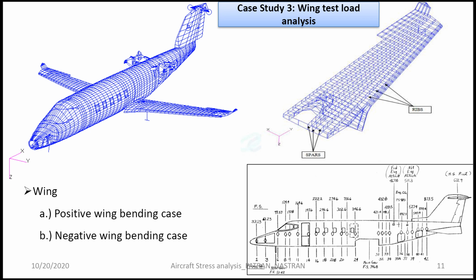So moving to another case study. I ran this global model, or the loads model, just to understand the deflection of the fuselage and wing, and to generate the test condition, that is, the aircraft being tested in the test lab, in order to generate those test conditions within the finite element tool using finite elements.